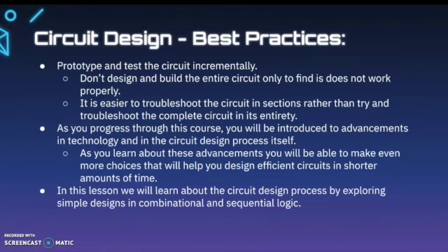When we're in the circuit design process, we have a few best practices that we should follow. First is that we need to prototype and test the circuit incrementally. If we design and build the entire circuit only to find that it doesn't work properly, it's much harder to troubleshoot than if we build it in sections and make sure individual sections work as we go along.